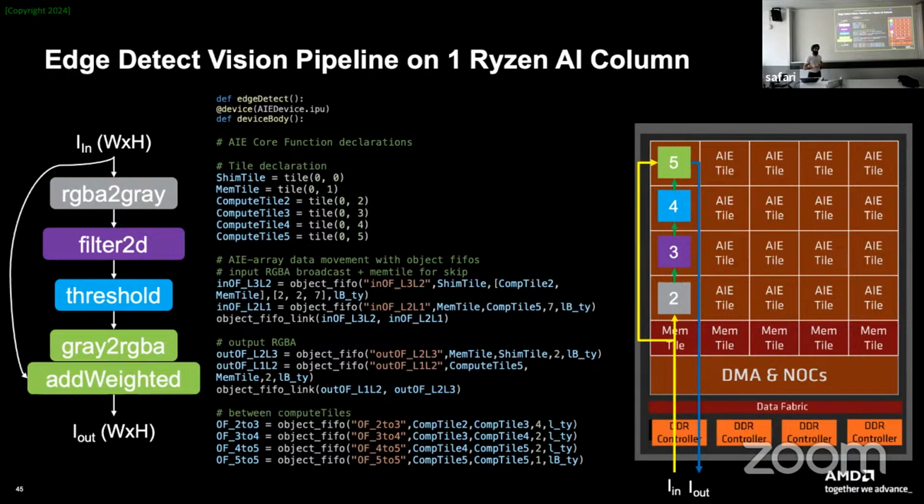When you use the shared memory of the neighboring core, you don't go through DMA. You have direct access to the neighbor, and in that case you don't use a channel, and we can do the skip connection. So you have to play around with the placement of the cores as well. And with even more complex scenarios, the placement becomes even more important to take into account.